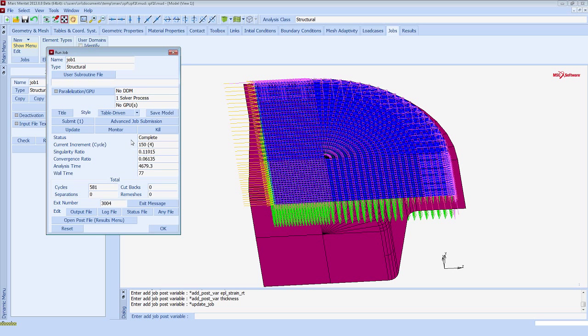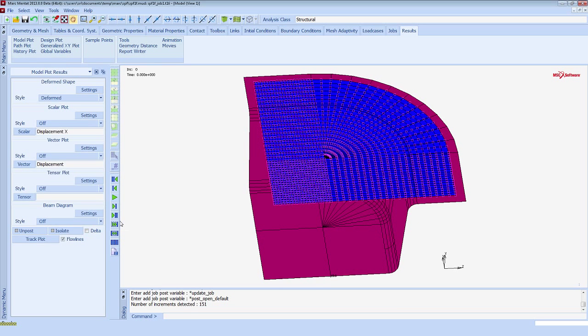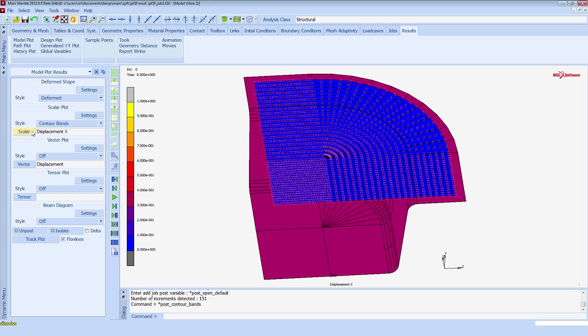As you see, I have already run this model, and notice that we specified a total of 7,200 seconds to run the process, but the job actually completed within 4,680 seconds. That's because here the completion criterion is that all the nodes are in contact. So since all the nodes are in contact at this time, the job is considered to be complete. Let me open the results file, and I will show a few quantities.